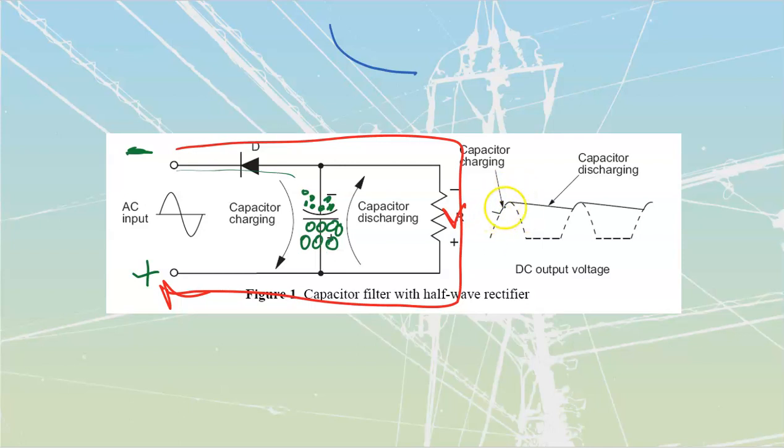What we get out of it is a curve that's going to look like this. What we're really looking at on each one of these, if you were to split one of these in half over here, is a charging curve, and then a discharging curve. Now, it's fairly flat. It actually does a little bit of a sag like that as it's coming across over there. But it is very much going to be these same RC types of curves that we were looking at when we were dealing with DC capacitance.